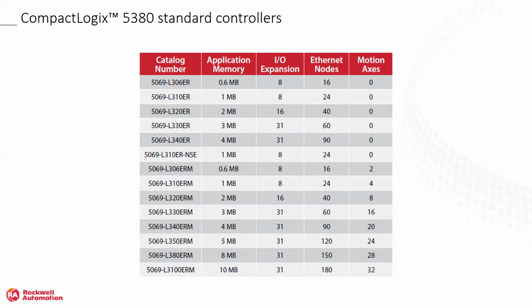You can, of course, do remote IO and bring in more IO, but if you want to just stack, you can stack up to eight cards on that CPU if it's a 306 or a 310. So it's important to understand that too, because when you build up your system, you find yourself with 9 cards, then you might want to move up to the 320 in order to not have to break it into another Ethernet remote IO rack.